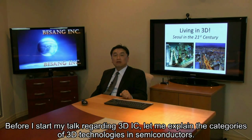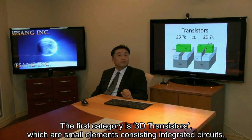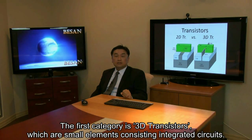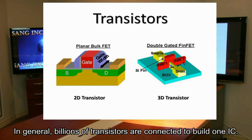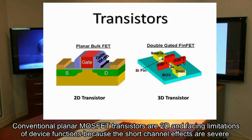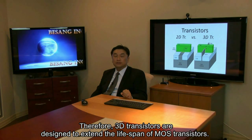Before I start my talk regarding 3D-IC, let me explain the category of 3D technologies in semiconductors. The first category is 3D transistor, which are small elements consisting integrated circuits. In general, billions of transistors are connected to build one IC. Conventional planar MOSFET transistors are 2D and facing limitation of device functions because the short channel effects are severe. Therefore, 3D transistors are designed to extend the lifespan of MOS transistors.